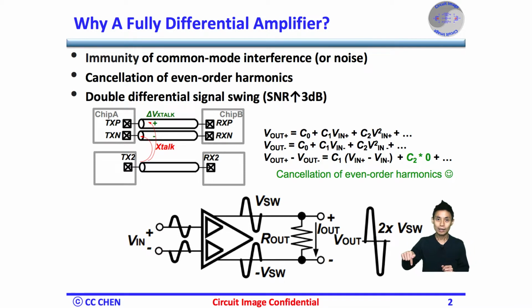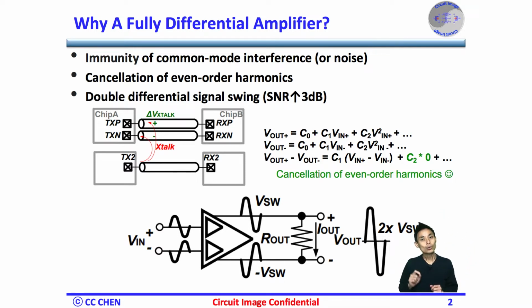With good linearity, we could make sure fully differential amplifiers would truly have twice the dynamic range compared to single-ended amplifiers. Of course, the twice swing comes from double the circuitry and power of a single-ended amplifier.